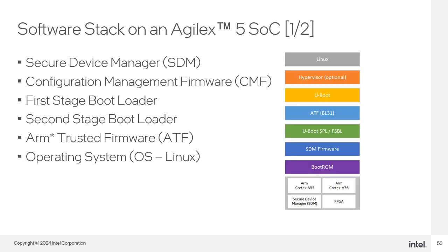Secure Device Manager Boot ROM. SDM samples the MSEL pins to determine the configuration scheme and boot source, and establishes the device security level based on eFuse values. SDM initializes the device by reading the configuration firmware from the boot source, authenticates and decrypts the configuration firmware, and starts executing the configuration firmware.